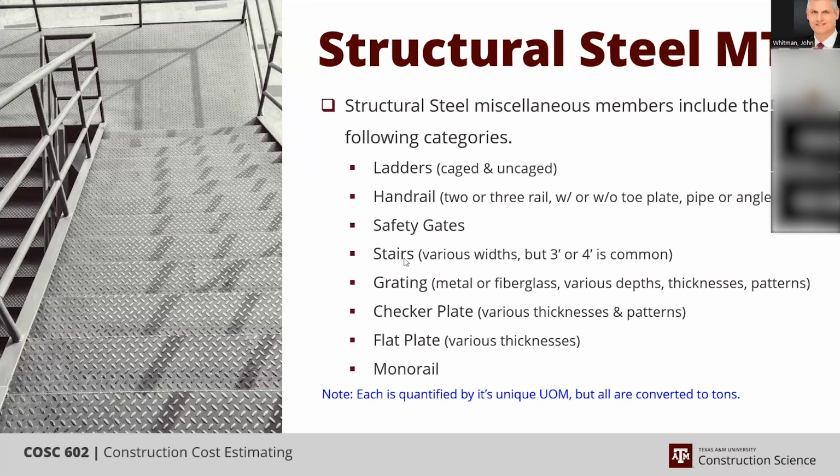And then the third is, if you have a, and I want to call it an allowance, but that's not true. If you have a weight per vertical foot, rule of thumb that you would use, then for every vertical foot, you're going to say it's so many pounds, and that covers all of it, except for the handrail again. So that's three different ways to approach the stairs.